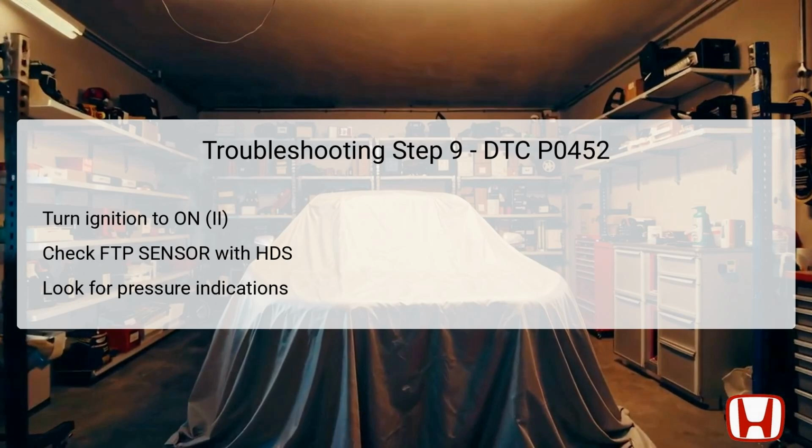You will be looking for the same critical pressure readings, approximately -7.3 kilopascal, -2.16 inches of mercury, -55 millimeters of mercury, or a voltage reading of 0.3 volts. If the values meet these specified parameters, it may indicate a successful sensor disconnection without any additional faults present in the circuit itself. If they are outside of this range, you will have to move to step 14 to investigate deeper into potential wiring issues or sensor faults that still require resolution.